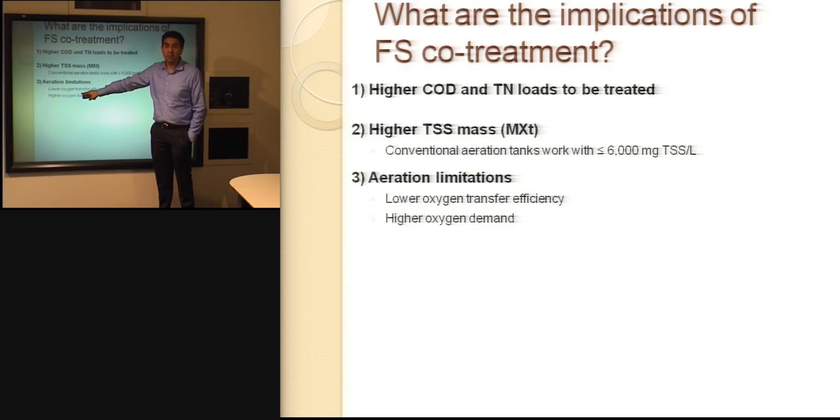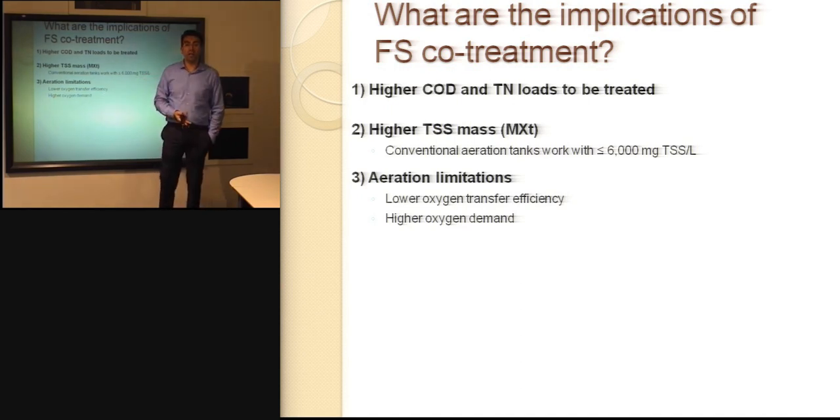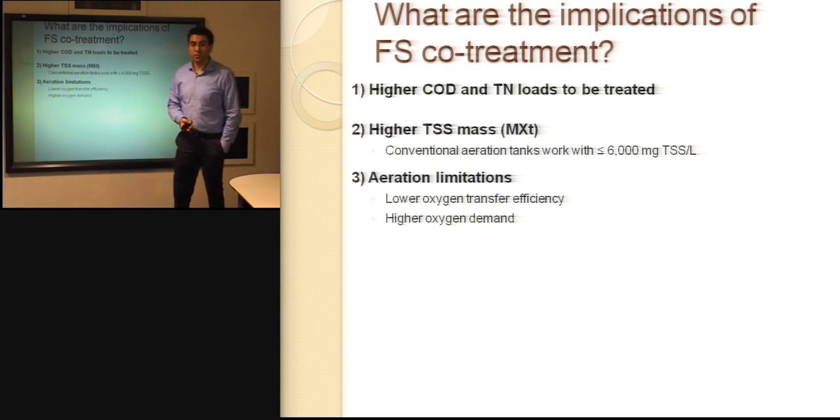That will decrease the amount of oxygen that we can transfer from the oxygen supply systems to the bulk liquid, and because less oxygen can be transferred to the microorganisms to degrade the organics, there will be a higher oxygen demand to compensate for that drop in oxygen transfer efficiency.